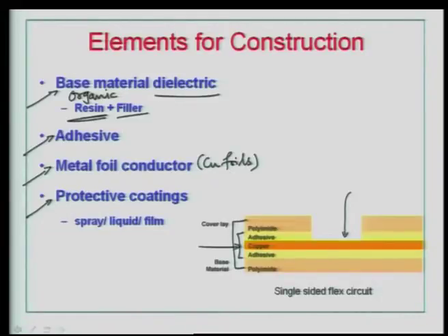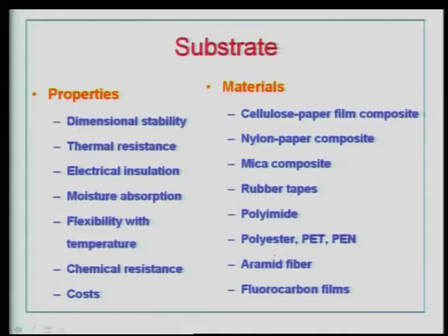Essentially, flex circuits are looked at as a connector to connector or point to point connection, rather than having a complex circuitry built on the entire body of the flex base. So, you can have the conductor lines. The copper represents the conductor lines that are defined by the design, the length and the width and so on. Single sided flex circuitry will have this kind of construction. The copper is protected by the polyimide dielectric and the adhesive material.